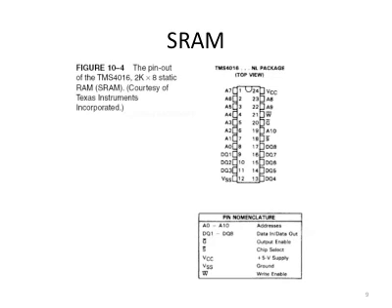Now we want to look at the second type of memory chips, RAM chip, and in particular this is the static RAM. In this example, we're looking at a TMS 4016 chip. And we know that from this 2K times 8, this chip has an 8-bit output. And again, it has 2K locations. So you will expect to see 8-bit data bus and also 11-bit address bus.